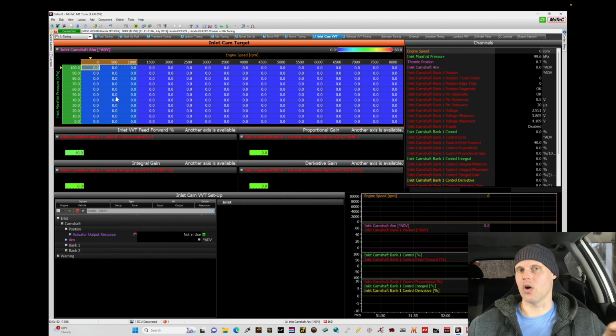When we start to drive off of idle, that's where we're going to start to introduce some overlap with the cam. Now we want to be specific with this. I am running OEM Honda cams, so the way I set this table up is going to be a little bit different than the way I would set it up for aftermarket cams that are hard on the factory tensioner or even upgraded tensioners. They can break the timing chain tensioner, cause you to skip timing and have valve to valve and valve to piston contact, all things we want to avoid. So how do we set this up?